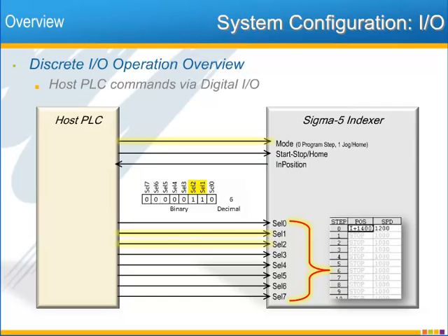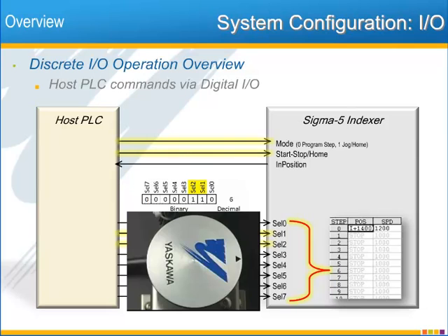After motion starts, the in-position output will be used to signal the PLC to indicate that the motor has reached the final position. This in-position is critical for the PLC to sequence other events, and it also means that no encoder wiring is needed between the PLC and the indexer. Just use in-position. So these are the basic control connections and the basic operation of the indexer.